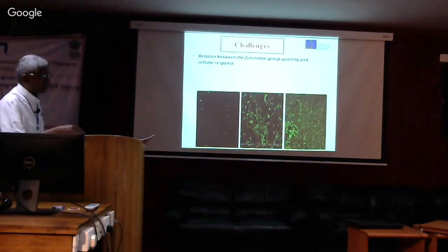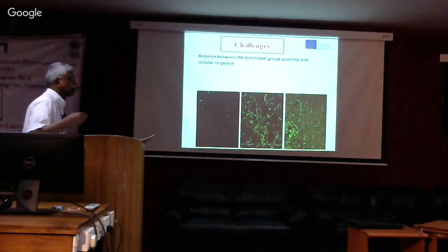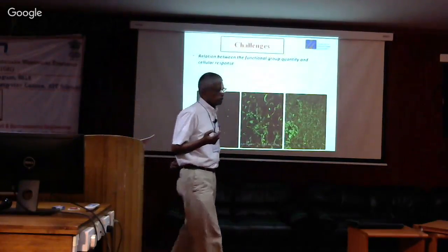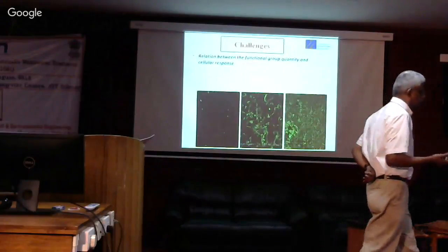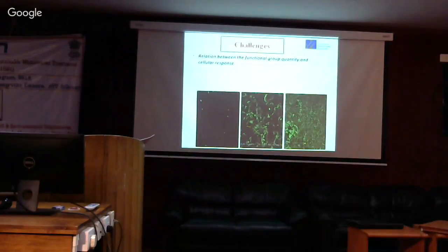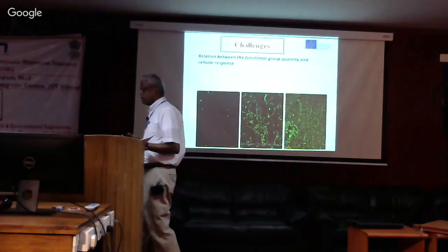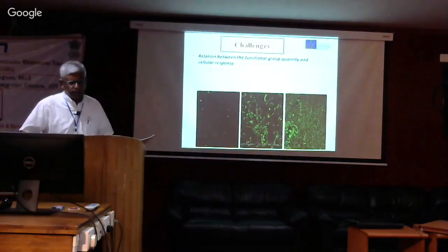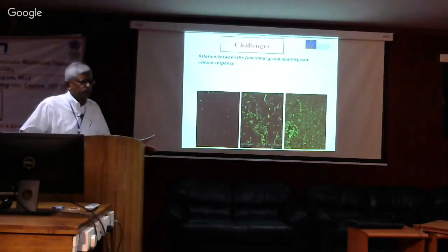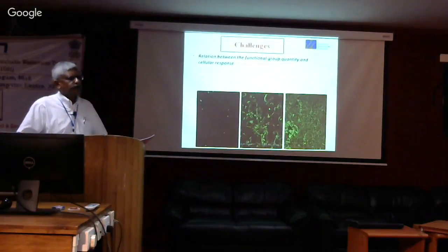Let's look at how you try to make it porous. How do you make it porous? Well, there are two possible ways. The one that we do is sonication. So you take this fiber and you put it in a sonication chamber, and the idea being that the sound energy waves would bombard it and would loosen it up. But, to put it very bluntly, we didn't really get much benefit from that.